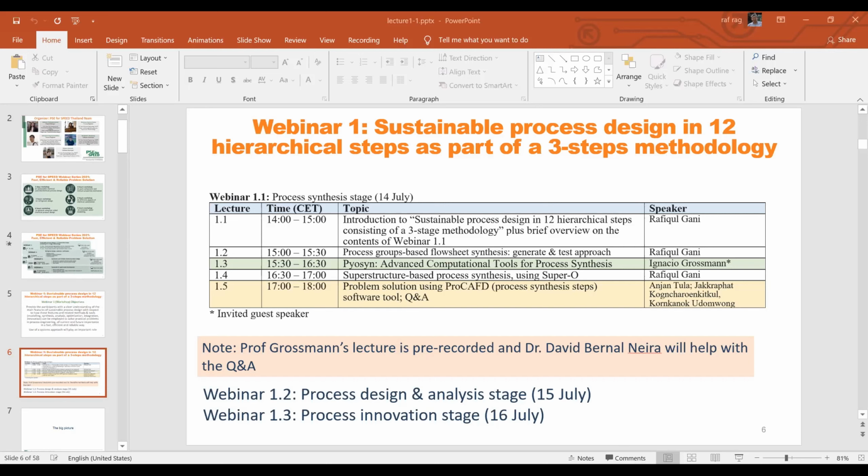Then no. Because in a distillation column with one feed and two products, one specification can be given at the top, one specification at the bottom. So it is one product recovery at the top, one at the bottom. And if it is the separation based on the binary pair, we suggest to use those two pairs as the key compounds to give the recoveries for them.